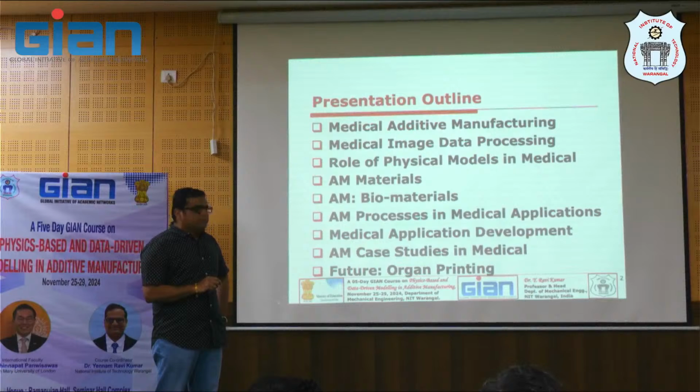And as we know, additive needs digital data. Digital data in medicine: now, thanks to computers, you have CT and MRI data. The medical image processing is now digital, and that is the start point of your medical application of additive manufacturing. You have either CT data, MRI data, ultrasound data, or PET, any scanning modality. DICOM is the one neutral file format, so you can get these medical images in DICOM form. Then those DICOM images will be imported to any one of the medical image processing software.